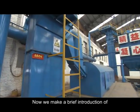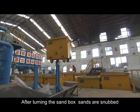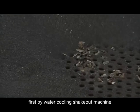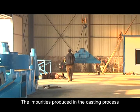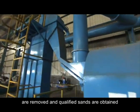Now we make a brief introduction of the sand processing flow. After turning the sandbox, sands are shaken out first by the water cooling shakeout machine and enter the screening conveyor. The impurities produced in the casting process are removed and qualified sands are obtained.